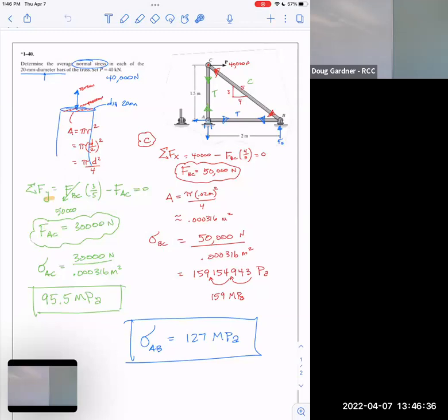Well, if I put a huge thick steel plate on top of this, that would cause the 200 to spread evenly across it. So they're saying average normal stress because you actually can't calculate every single differential element, every single square inch of this may not be the same. So that's kind of interesting.